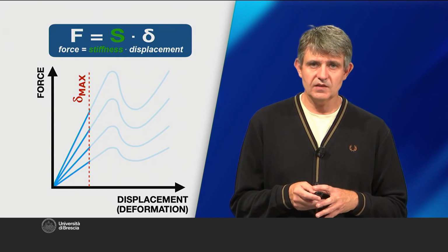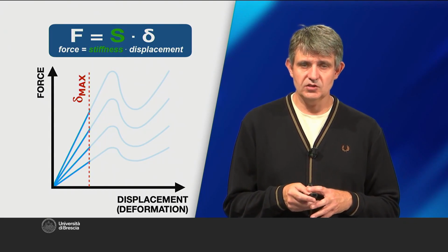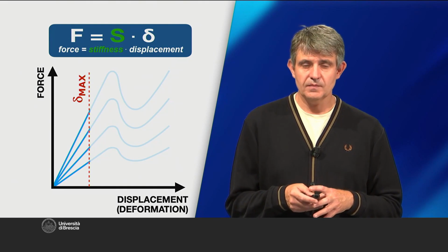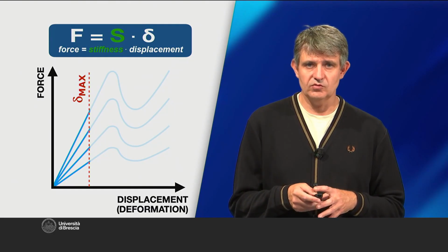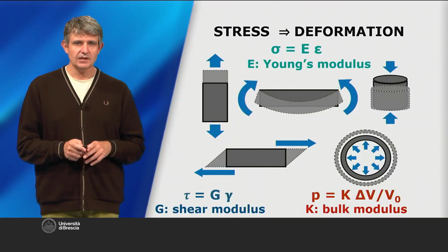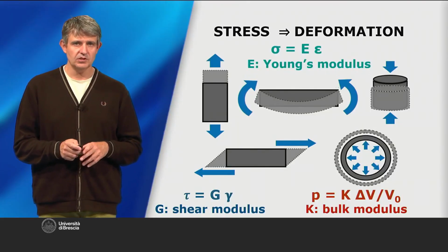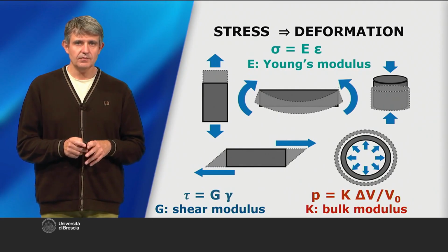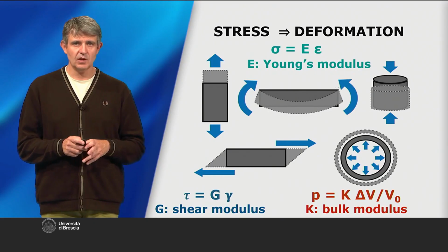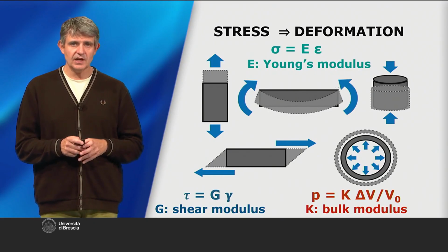It's important to clarify that when designing a structure to be sufficiently rigid, the deformations involved are generally quite limited. In particular, they're well below the levels that would cause permanent deformation or failure. The design is done within what's called the elastic range. The strength of a manufactured object depends on both the material and its geometry. The stiffness of a material, on the other hand, is an intrinsic property of the material itself and is defined as the ratio between stress and strain.